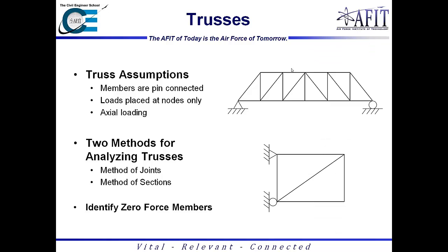So the next big one you're probably going to see on the exam, in fact, I can all but guarantee it, is you will see a truss problem. There are a couple assumptions we make with trusses. We assume that the members are pin connected, and that loads are only placed at the nodes. We also assume that the forces in the members themselves are only axial loaded.